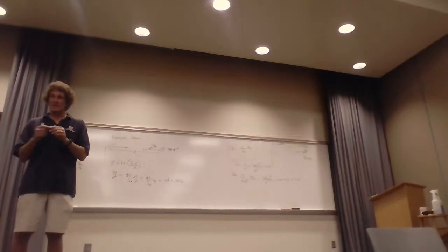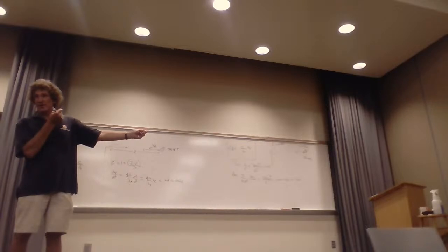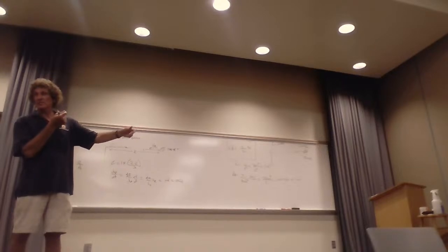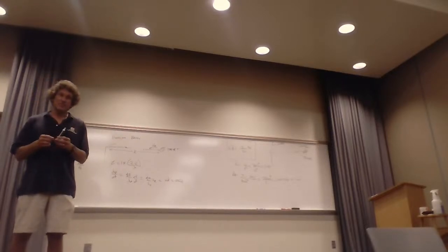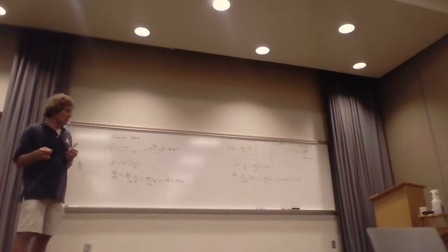It's taking a snapshot in time of the signal that you're feeding into it from your antenna, and then it does a fast Fourier transform, and then scales it appropriately. Now, you all know what a fast Fourier transform is, digital Fourier transforms. They really allow you to do the same thing as a continuous time Fourier transform does, but in the digital domain, and they give you a lot of information pretty quick.